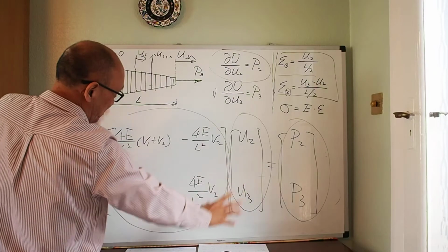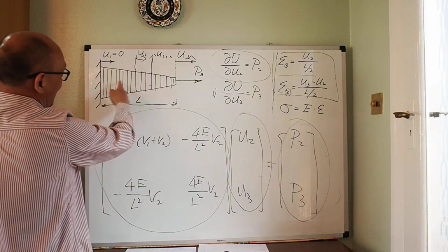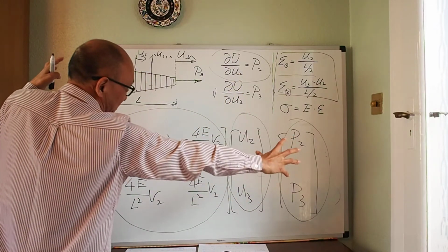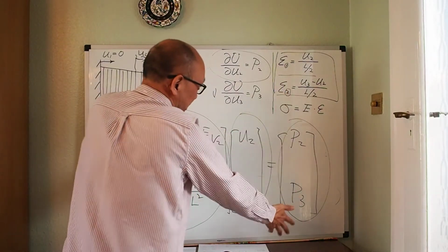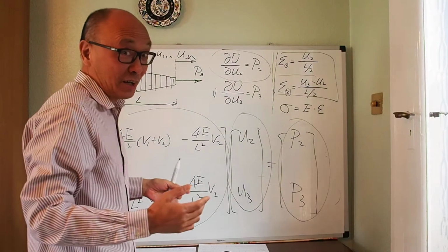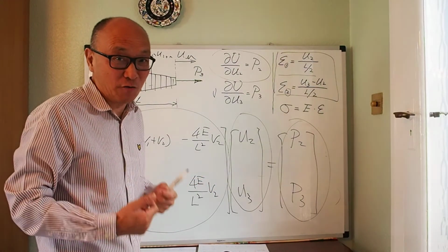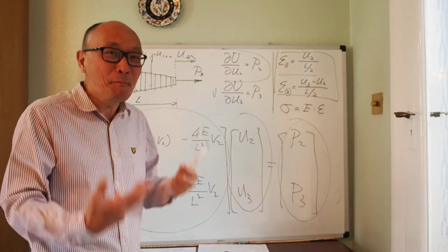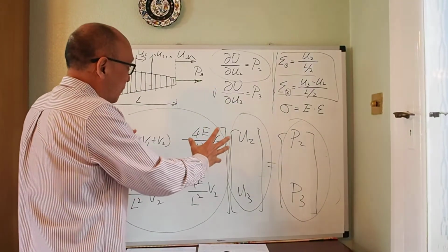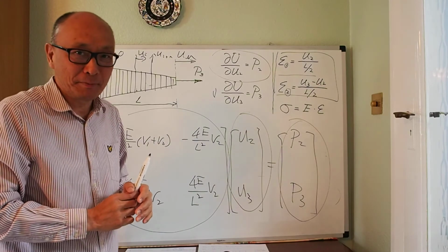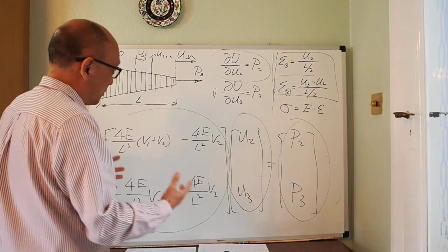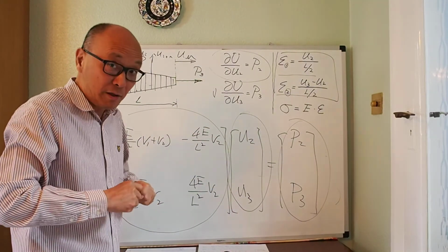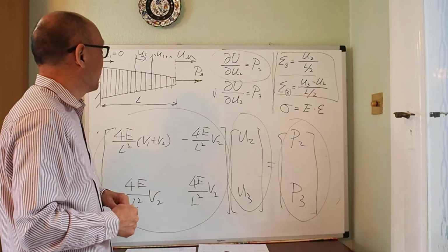It's just that the equations get messy. Instead of just 2 unknowns here, I may have 20 or so. So there will be 20 or so unknowns, and this matrix gets bigger, 20 times 20, and the force matrix gets bigger. Then you can't solve that by hand. You have to solve it using a computer. And that's why the finite element method only became powerful in the computer age. To solve a problem accurately, you have to use a computer to solve the large linear simultaneous equations. But the fundamental idea is actually quite simple.